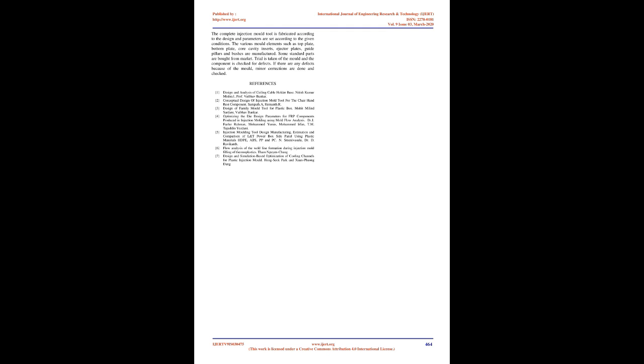Ejection system. A mechanism is always needed to push the component out of the mold. This is called ejection system. There are various ways ejection is possible, such as pin ejection, sleeve ejection, plate ejection, air ejection, etc. For this mold the common type is used, i.e. pin ejection. This involves pushing the component out by force by circular steel rods known as ejector pins. The pins are headed and fitted in the ejector plate supported by ejector back plate. Ejector pins slide in the mold plate by a good sliding fit.